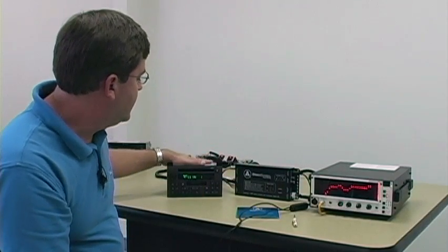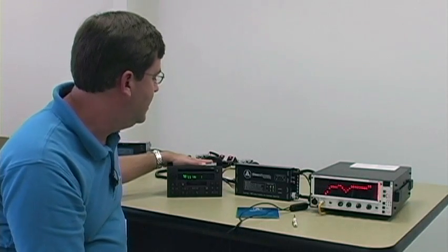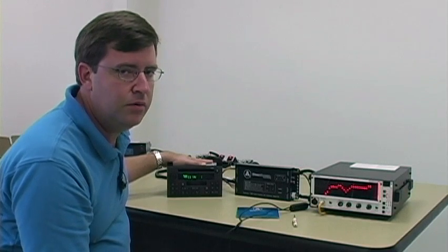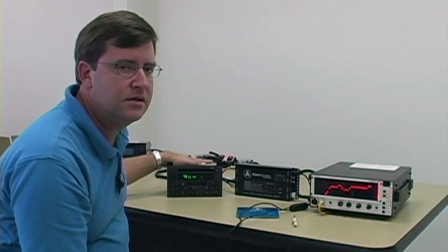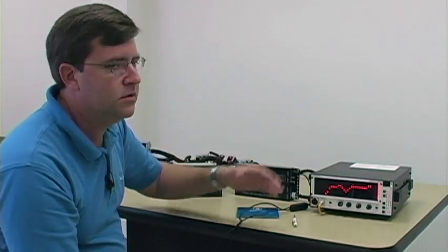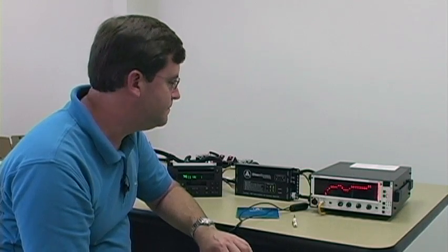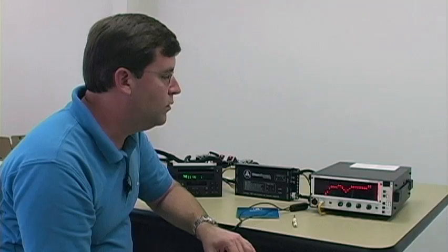Now in this particular case, this Lincoln radio, as with most Ford premium systems, has a dedicated subwoofer output coming out of it. We need to take that subwoofer signal and add it to this front signal and also add it to the rear signal so that we have full range and the CleanSweep can do its job and flatten that response.